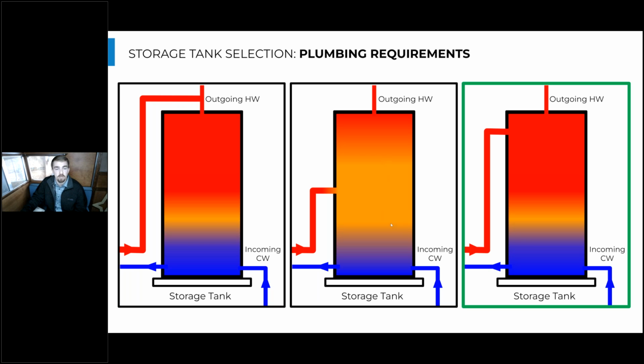But as soon as this tank starts to draw down and hot water is being sent out to the building, this cold water will backfill up into the bottom. And as soon as this cold water reaches that inlet from the heat pump, the cold and hot water will mix and make this warm water that may be cooler than what the occupants can handle or what is acceptable for them.